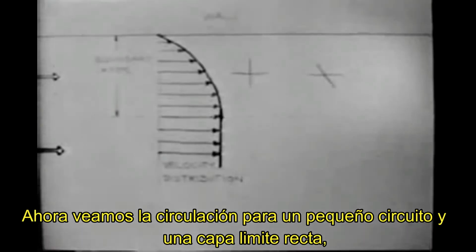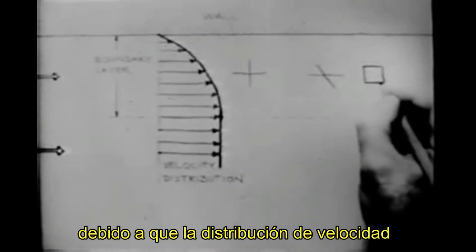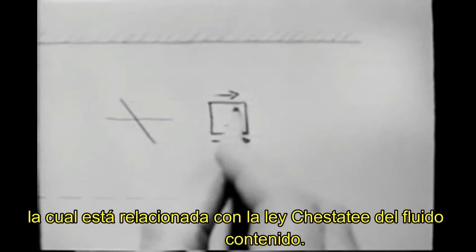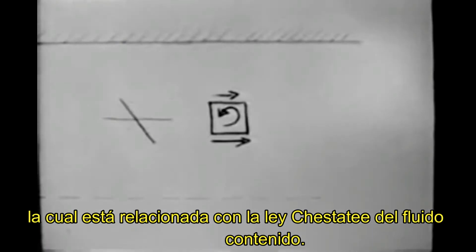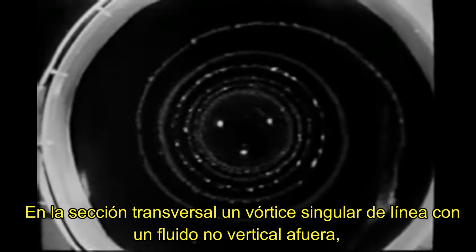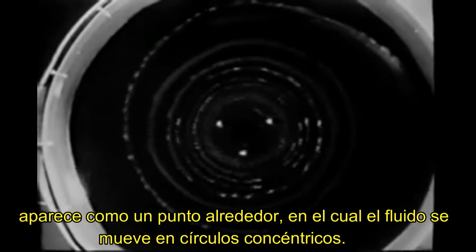Now let's look at the circulation for a small circuit in the straight boundary layer. Because of the distribution of speed, there is a net circulation, which is in fact related to the vorticity of the enclosed fluid. In cross-section, a single vortex line with non-vortical fluid outside appears as a point around which the fluid moves in concentric circles. The velocity varies inversely with radius.